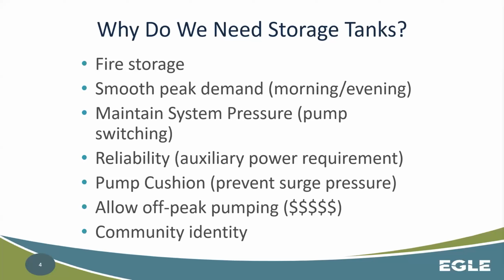Smoothing out your peak demands, whether that's the morning or the evening peaks, so you're not having the pumps doing all the work. You have that storage on hand. Maybe your well capacity or treatment plant capacity isn't able to keep up with those peak demands, but with enough storage, you might be able to overcome that, or ideally it would be designed to overcome those things. Again, maintaining system pressure. That's going to be the main focus of this whole presentation.